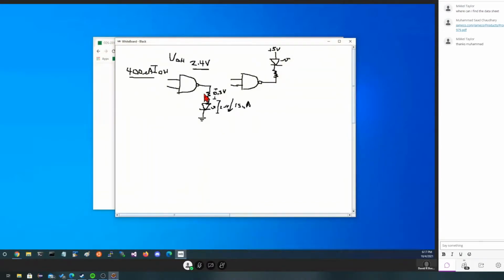So at 2.4 volts, which is when it's high, and we have to have high because of the direction we pointed the LED. We pointed it toward ground. Now let's look at the other case where we are hooked to 5 volts externally, and we're going to have 2.1 dropped here, 2.9 dropped here, and the current is going to flow that direction.